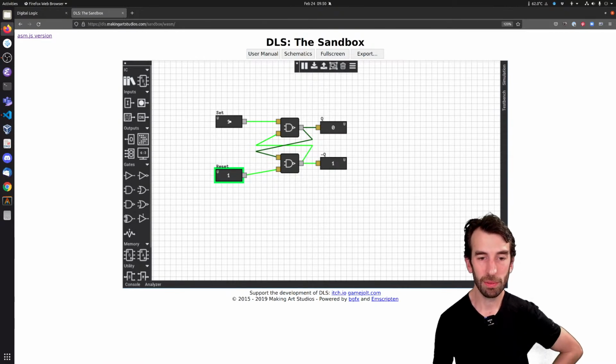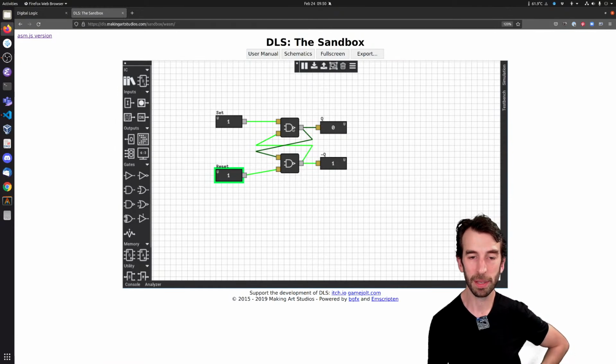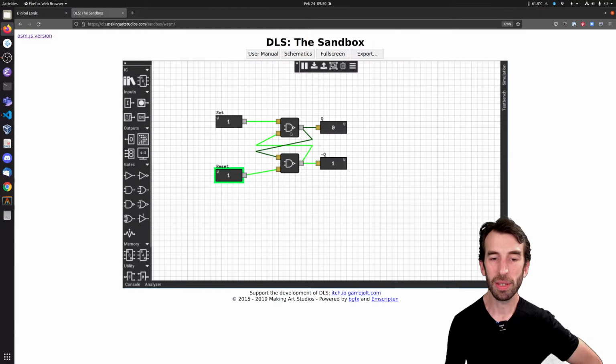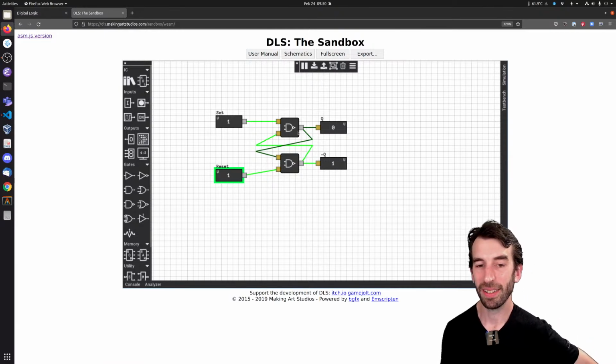So we've got a very fun little device here. Should we just have a little look and see how it works? When I've got 1 and 1, those two lines are, well, this line's active. Let's not talk about this line for the moment. We know that a NAND logic gate is active in all states except the state where both of its inputs are 1.